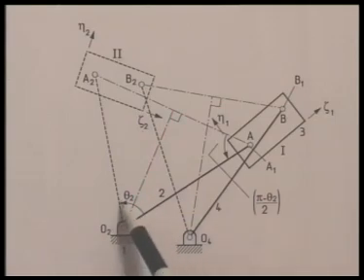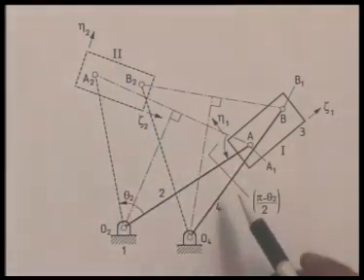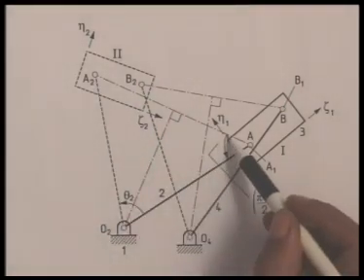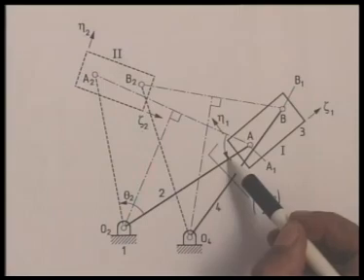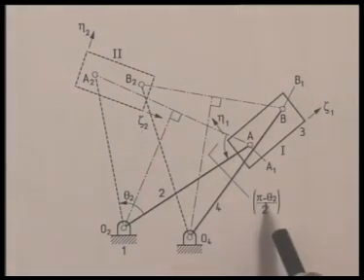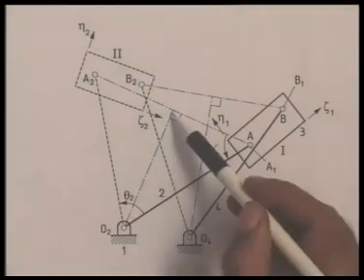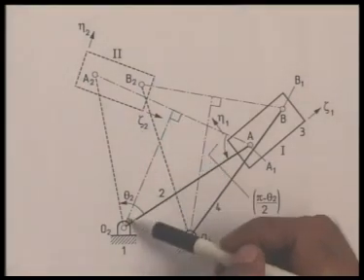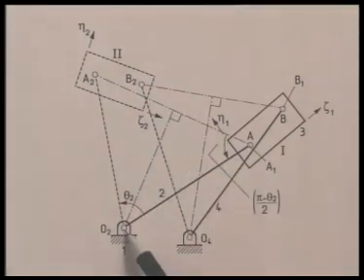To make this angle theta 2 between O2A and O2A2, we draw here at the point A a line at an angle (pi minus theta 2)/2, and that line intersects the perpendicular bisector which was drawn earlier at O2. So that decides the location O2.